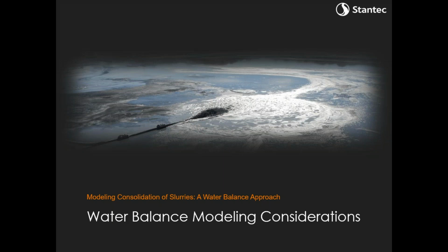Really, this permeability curve that we showed is very much a material specific property, right? Like I mentioned before, if we have a clean sand, potentially an ASTM C33 kind of sand, very strictly controlled, that sand is going to have a higher permeability than something that has a silt or a clay mixed in with it, just as this person was asking about.